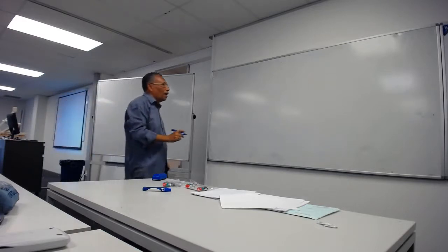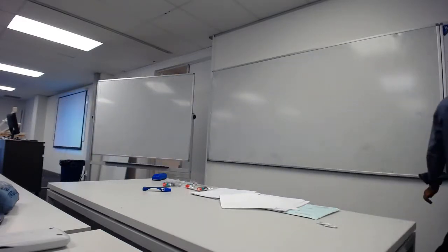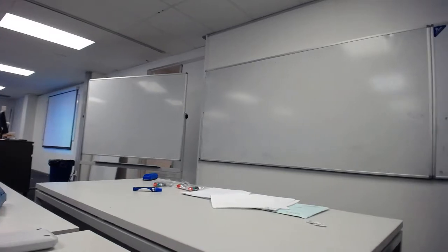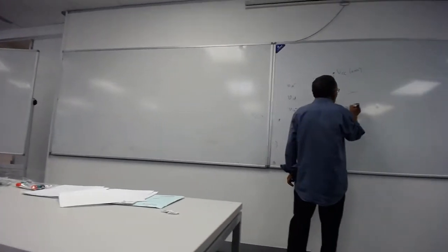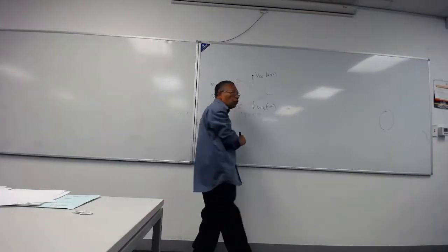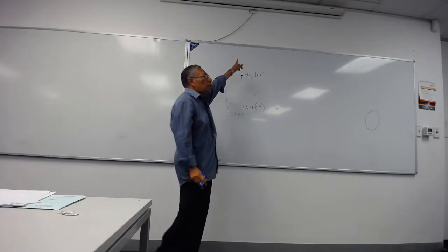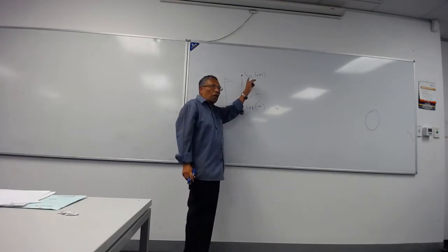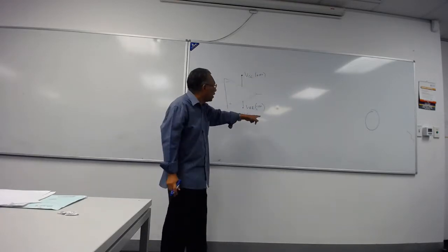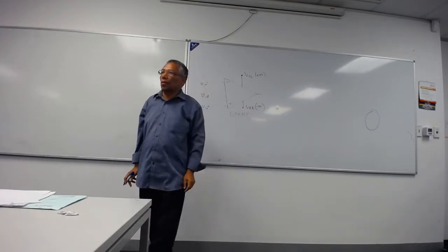An op amp also has two supply rails, your supply voltages, VCC and VEE, which are approximately plus 15 volts here, in this specific case, and minus 15 volts here. So it gets clipped to what? Exactly, clipped to that. So if the output goes very high, it will get clipped to this, or if the output goes very low, it will get clipped to this.